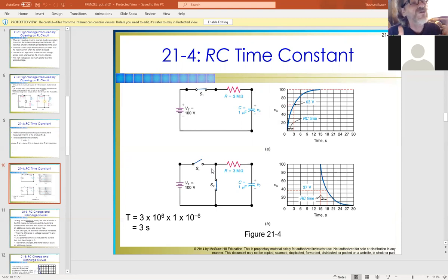I used to have a really, really big ceramic resistor that could handle some major power, and I soldered 2 leads on it. What I used to do is, when I got these things in, I would bleed off all the caps. You had to be careful. You don't want to touch these. There's 400 volts. It might not kill you, but oh my God, you'll wish you were dead after you got hit by that. It's like getting kicked by a mule. That hurts a lot.